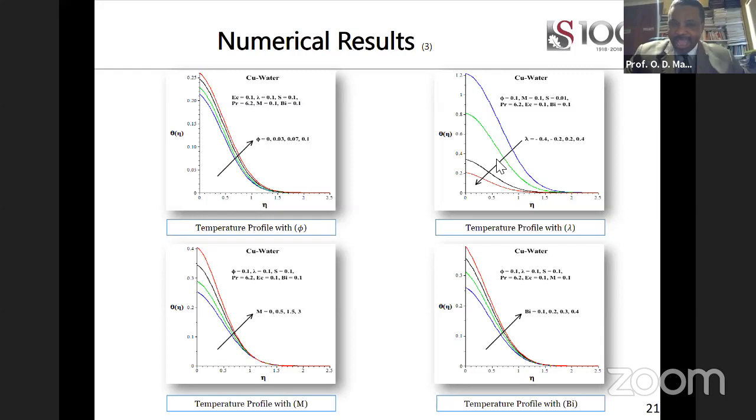When it's shrinking, why? Because there is the issue of interaction. You are having reverse flow and forward flow. Everything is interacting. Therefore, it generates more heat due to high shear rate. So you see that for a shrinking plate, the temperature is high. For stretching, the temperature of the fluid is lower compared to when it's shrinking. And this increase in temperature is due to high shear rate in the fluid, because the fluid close to the surface is trying to move backward because of the shrinking, and the other fluid wants to move forward because of the stagnation flow, trying to move away from the other part of the plate. There is high shear rate taking place, which creates more viscous dissipation in the system, and additional heat and Joule heating as well.